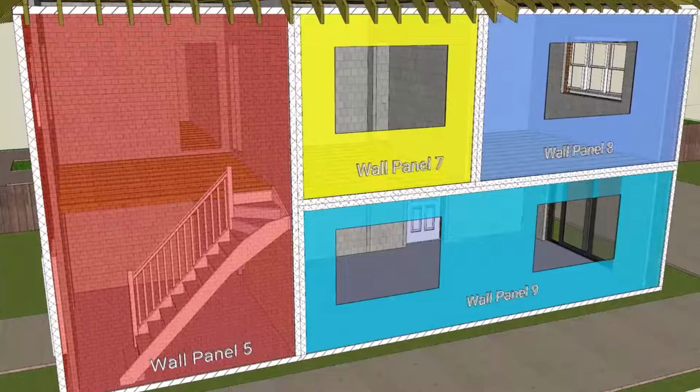Yep. I should mention that the joists in this case are not running directly into the wall panel, so the engineer will have to detail this such that the wall abuts the floor joists and the wall can get restraint from the floor joists. This detail is not shown here, but for example, you may expect to see some noggins on the floor joists in reality, and some strapping to the inner leaf of the external wall.